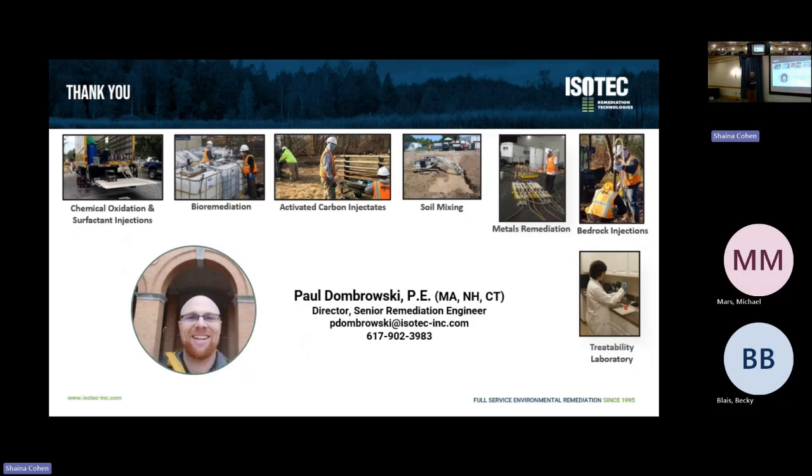The solid substrate ones, I've seen numerous examples for ZVI and wood chips lasting 10, 15, 20 years, but eventually they still may need to be refreshed. And for some of those, if it's a wood chip barrier for reductive dechlorination, you could inject EVO right into the wood chips themselves. Because you already have this barrier, it's more permeable than surrounding groundwater, so you just put new hydrogen and electron donor into there.